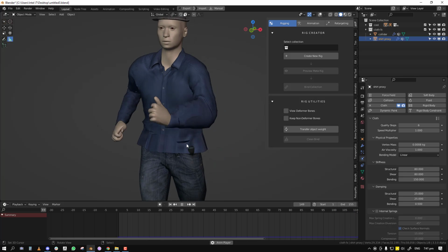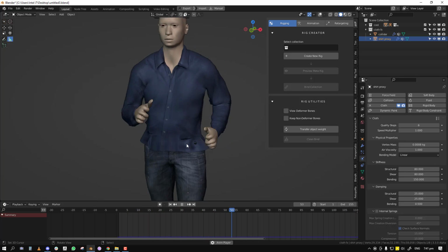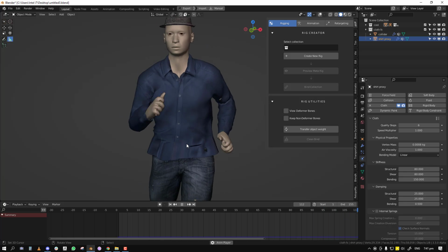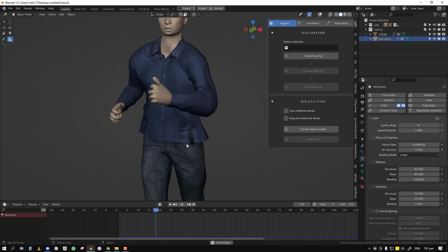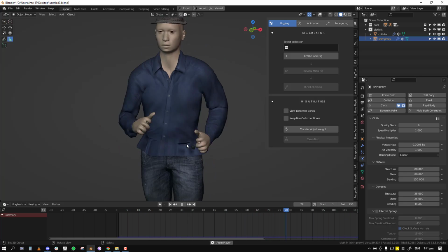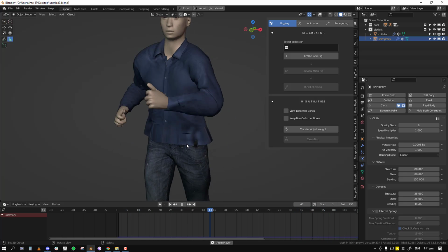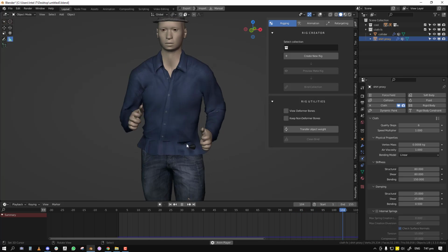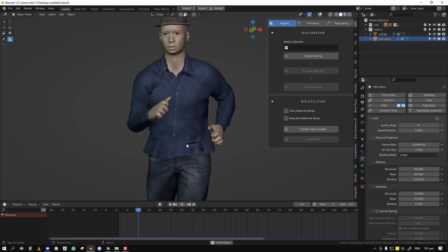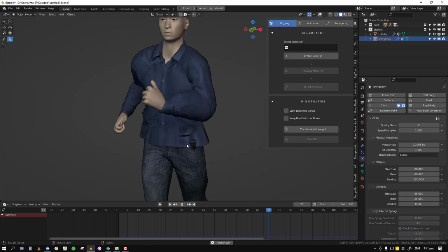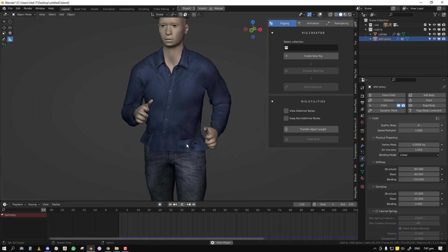Yeah, so that will be it for this tutorial. Certain things didn't go as expected, but I promise you this actually works, especially for the surface deform modifier. So to recap, you have to first close the holes, you triangulate, and if you don't want to decimate, that's fine, but decimating is the main point of the optimization process.